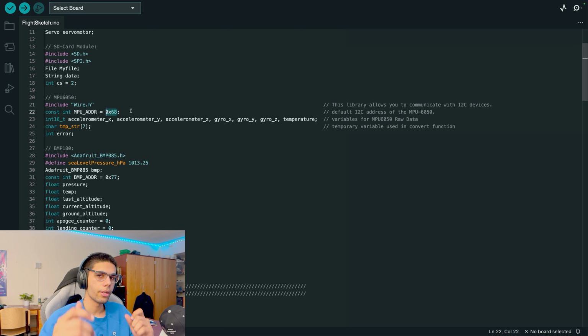If you remember in the previous session, I talked a little bit about memory and registers in the memory, right? So the data from the sensor is actually stored temporarily in those registers. This is the memory address of that register. How do we know which register to access? Every register has a unique address. So this is the address where the MPU 6050 is available.